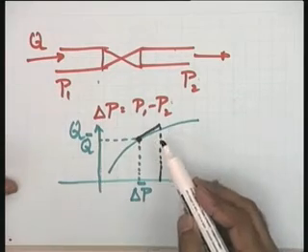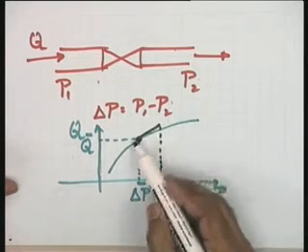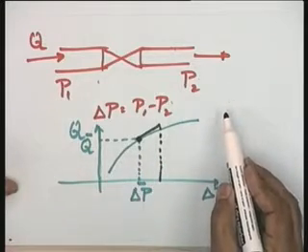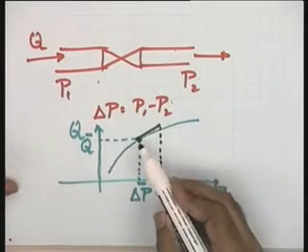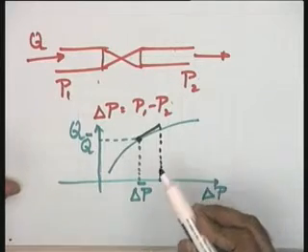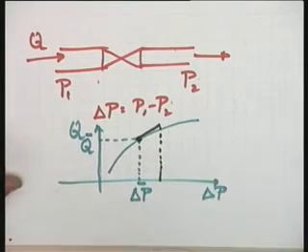So, it means this approximation or assumption which I am making, that this is a small deviation around the equilibrium point, though it is a highly nonlinear curve. You may please note that it is not a big assumption if this model is being derived for a feedback control system particularly. If it is an open general model, your mathematical model is in doubt.